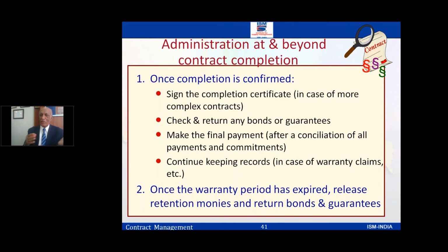And the next is continuing keeping records around. Once the warranty period has expired, release retention money and return the bonds and guarantees around. So keep in mind that this has to be returned.